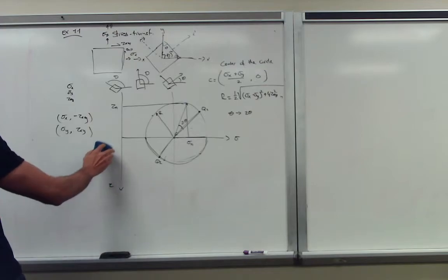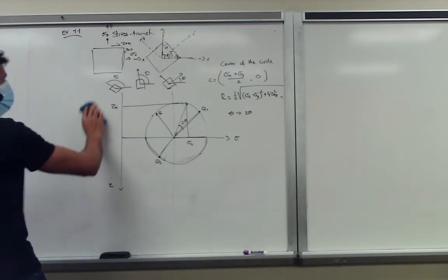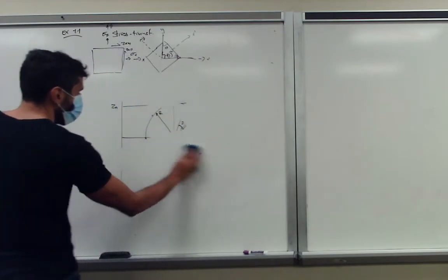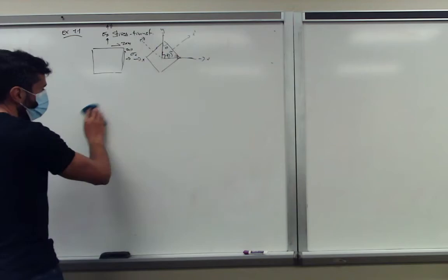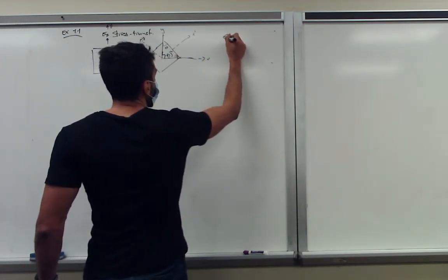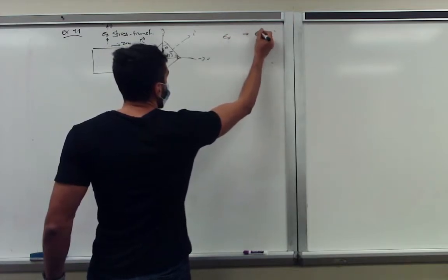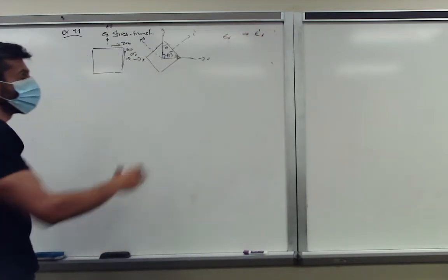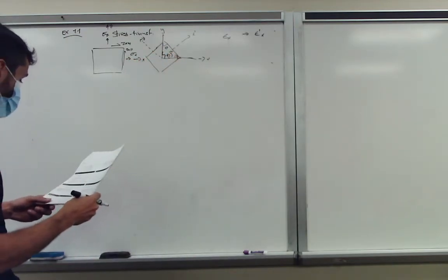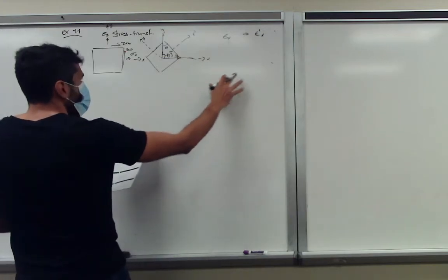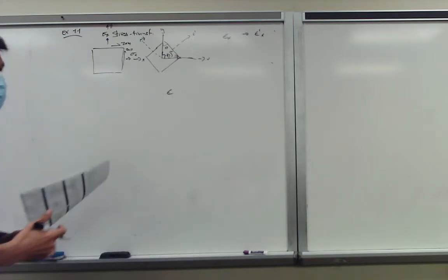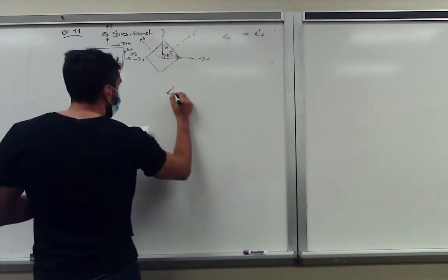And of course, what we discussed was stresses: sigma x, sigma y, and tau x y. The same can also be done for strain coordinate systems. So we can go from epsilon x to our new coordinate system, epsilon dash x. I will just give you those for epsilon x, but you can start out with the same principles, write the equations, and come up with a transformation matrix.